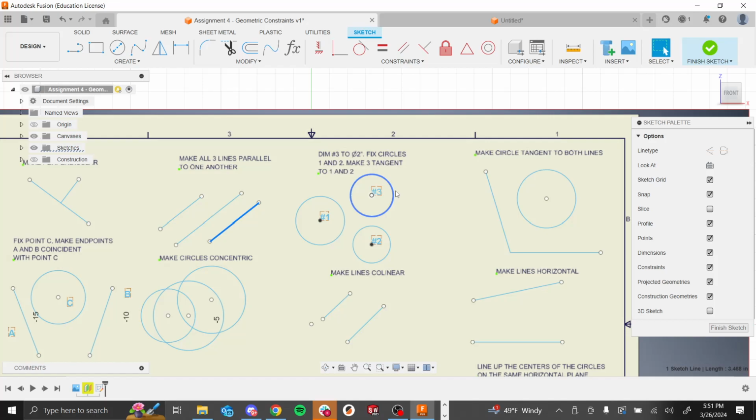Yeah, that's basically the same. But concentric is just making sure the arcs of the circle are centered around the same center point. So it's useful for, let's say you have a bolt hole and you want the cap of the bolt to go into your part. You can make a concentric circle that's a little bit larger than the bolt diameter or the head diameter, and then that way it'll be a nice recessed hole that's centered.